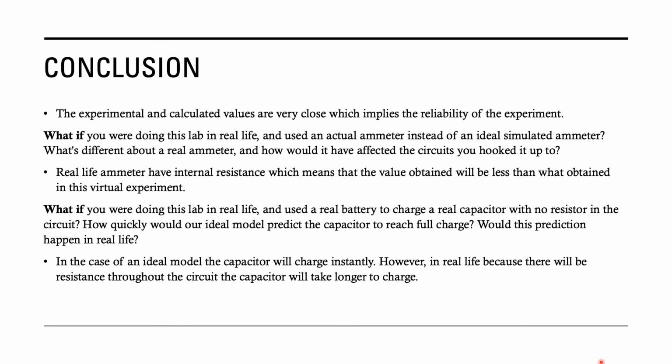and used an actual ammeter instead of an ideal simulated ammeter? Real-life ammeters have internal resistance, which means that the value obtained will be less than what was obtained in this virtual experiment. What if you were doing this lab in real life and used a real battery to charge a real capacitor with no resistor in the circuit?